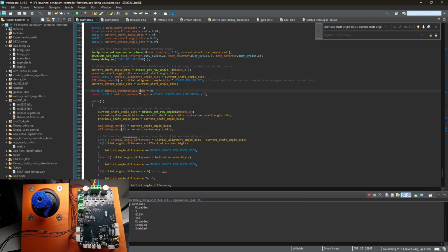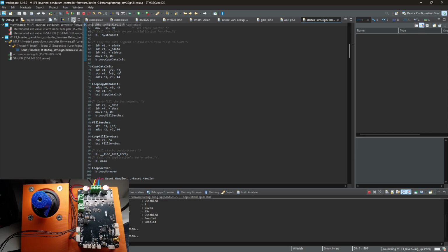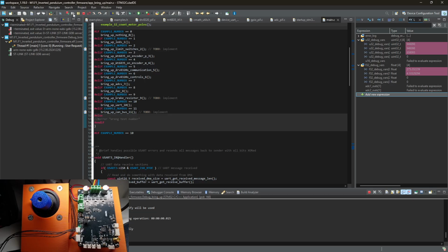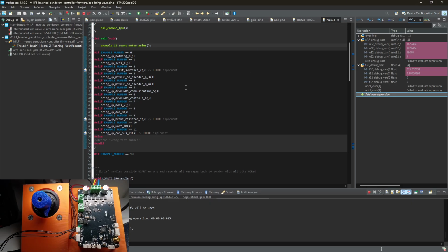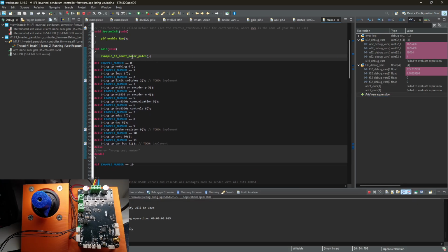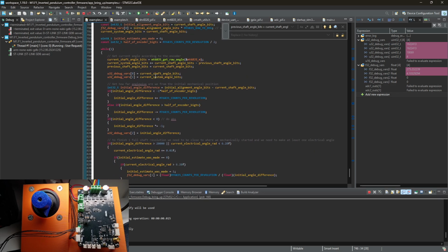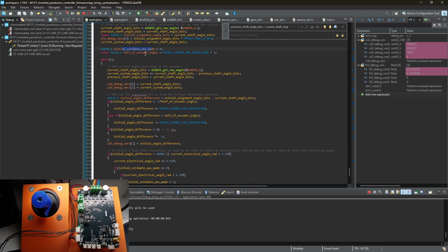Then, okay, and if estimate was made, let's run it. Run. We need to see a full revolution. And we see the estimate of 4 pole pairs, which is right. Okay. I didn't break anything. Let's go back. Didn't break anything. So here an estimation was made and half was encoder built.